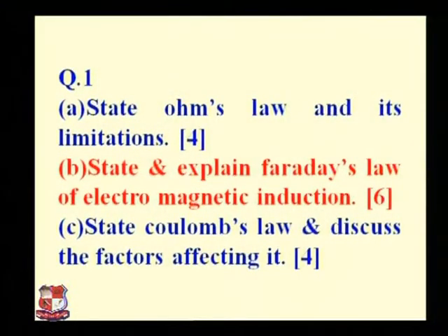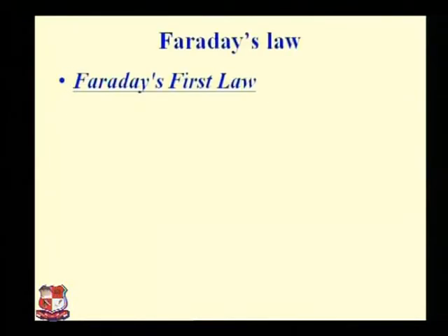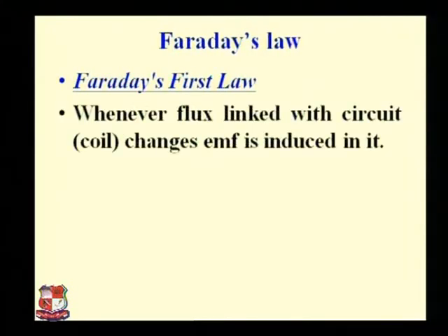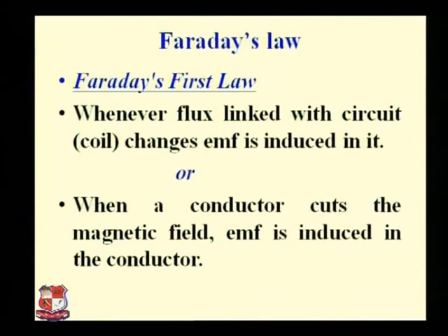Okay, next question. The next question is: state and explain Faraday's law of electromagnetic induction. It asks for 6 marks. So Faraday gave two laws for electromagnetic induction. Faraday's first law states that whenever the flux linked with a circuit or coil changes, EMF is induced in it. Or in other words, when any conductor cuts the magnetic field, EMF is induced in the conductor.